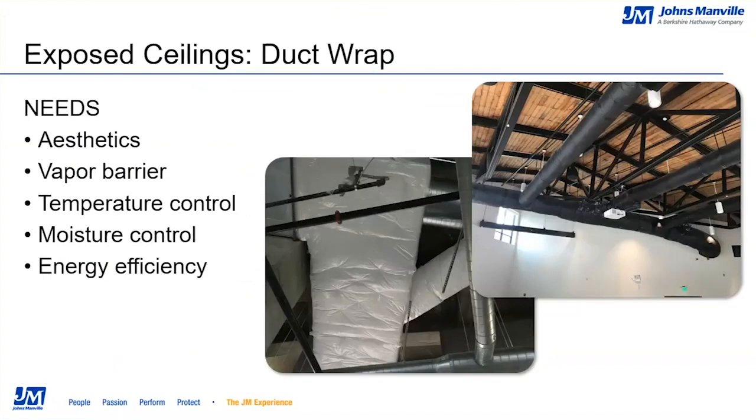So that being said, what insulation materials out there are available that will allow you to insulate your ducts without detracting from the aesthetics of your application? We're going to start with the newer products on the market that are designed for applications just like exposed ceilings. In some cases, you'll choose to insulate exposed ductwork with an exterior blanket or duct wrap.